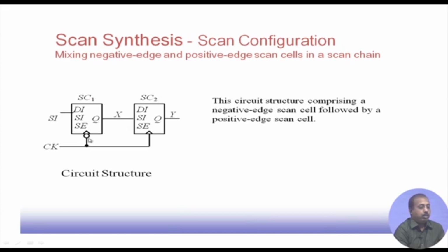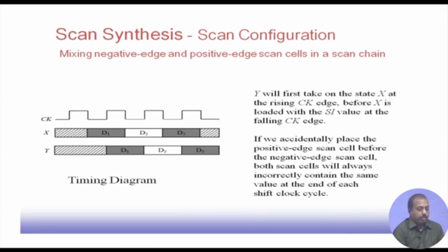So, whenever I have two types of flip flops getting mixed, negative edge triggered and positive edge triggered, the design synthesis should always put the negative edge triggered flip flop first and then the positive edge triggered flip flop, otherwise there will be a problem.